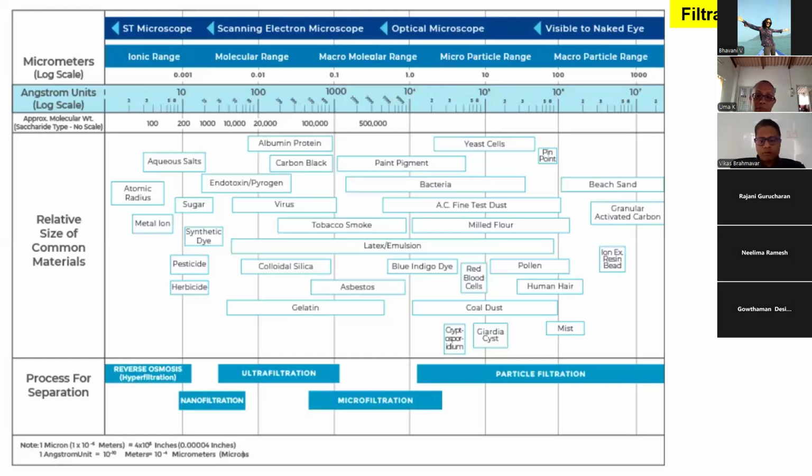So for those of you who want to understand it a little technically, this sheet can be used for deciding what contaminants are there in the water. But generally, when a laboratory gives a report, they give this 14 parameter report. Based on that, you generally won't know. But if there are heavy metals, metal ions, if you have cadmium in it, then it means metal ions. Even if your TDS is 300 ppm and it says traces of cadmium, you can't do anything. You have to put an RO, because metal ions don't get removed by anything else, right?